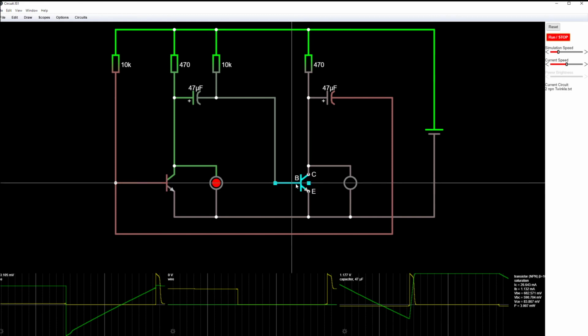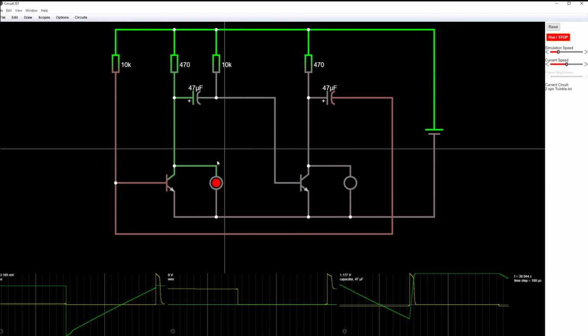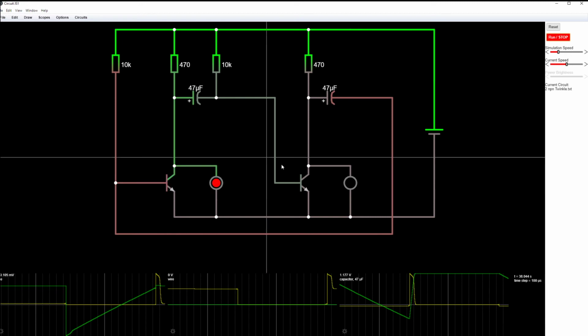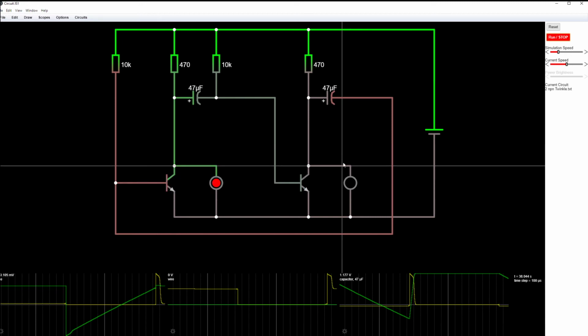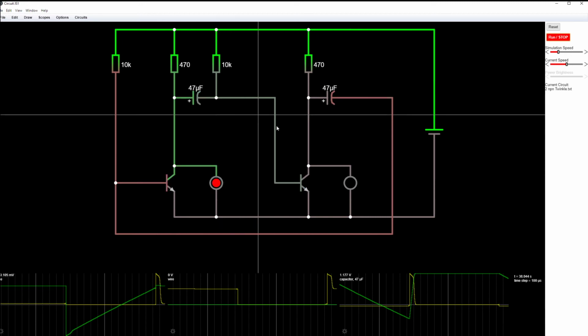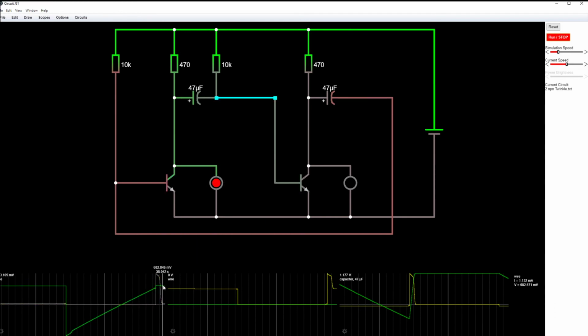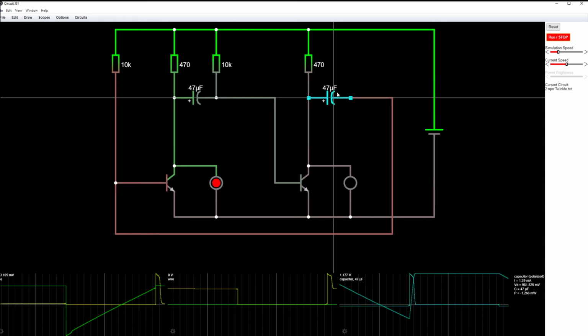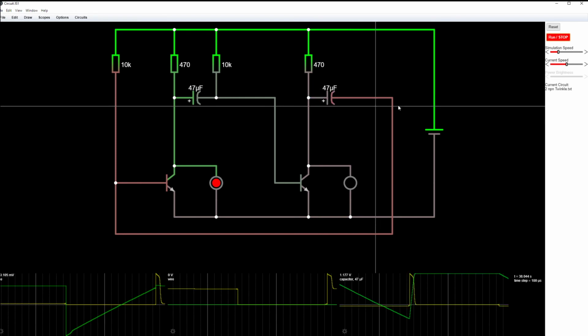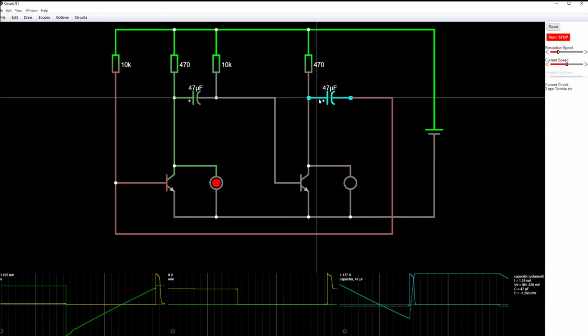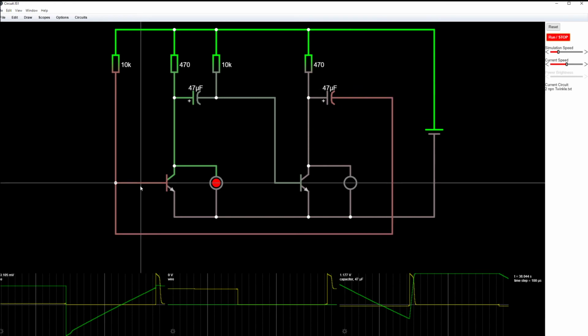So we can see here the reaction is between these two transistors, because the transistor will turn on when it gets 0.7 volts to connect to it. It needs time for this capacitor to recharge up to change the voltage between both sides to allow it to have 0.7 volts to go into it.